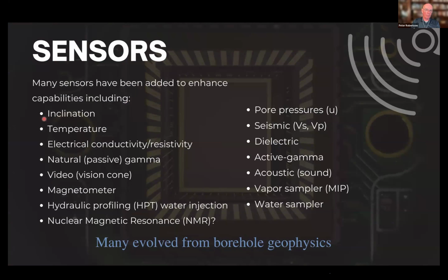And for many operators, if you hit something like a boulder and the cone suddenly gets deflected, then a sudden change in inclination is a warning that you may in fact damage a rod, and you may break a rod. And so if there's a sudden change in inclination, then typically you stop and pull out and then move over a short distance and go back down again to avoid hitting whatever that hard object was.